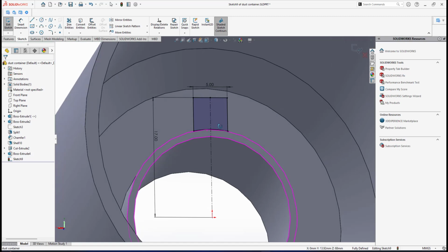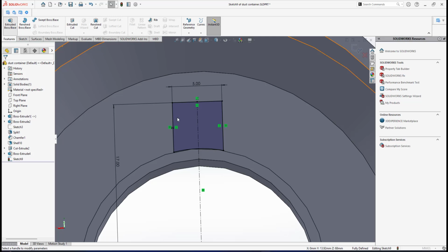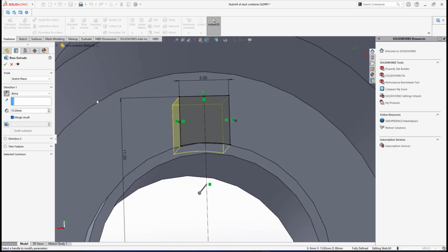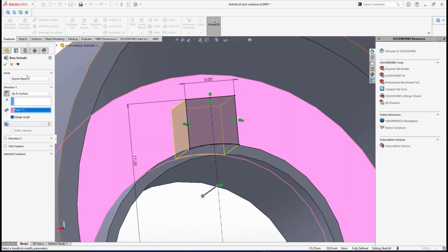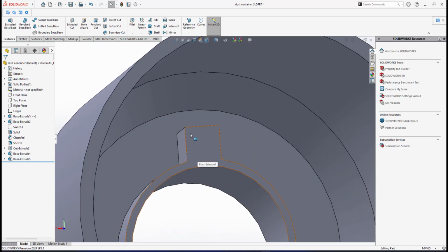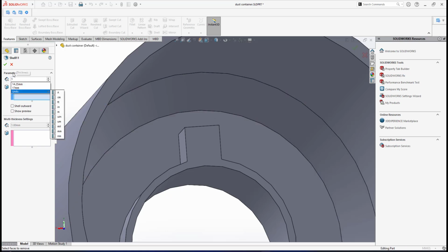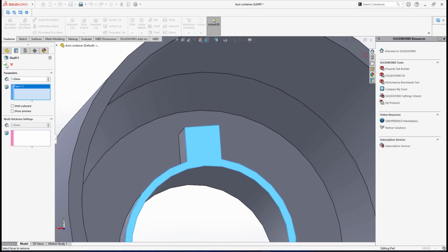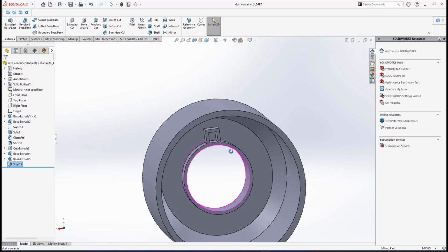So what I will do here, I will do extrude, and it goes to this, it will stop at this surface. It will start at this surface, and okay, I click OK, but I need to create a hollow thing, right, by a thickness of 1. So it means that I will do shell of 1 millimeter, then I will select at the surface, so we have this thing, right? Okay, so we have features.